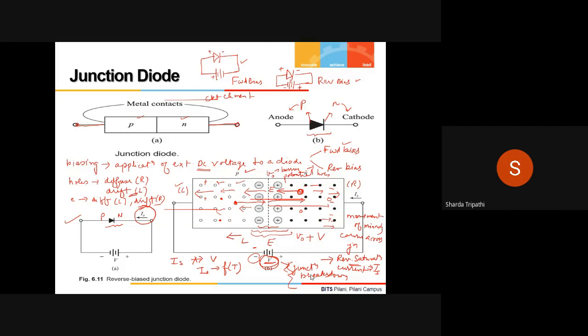So do not worry about this, Abhi, because while we study the Zener diode, maybe in the next class or the next to next class, we will study this in great detail. The point over here is that breakdown is not always a bad thing because it helps to devise special applications of the diode like a voltage regulator. When we study the voltage regulator, you will see that in this case the diodes are always operated in the breakdown region because it helps to maintain constant voltage across the load. But in the general case, because here we are not talking about the breakdown at all, we just mentioned it as a special phenomenon. So in general, we do not want our diode to go into the breakdown region. Therefore, it is essential that we choose this value of voltage carefully.